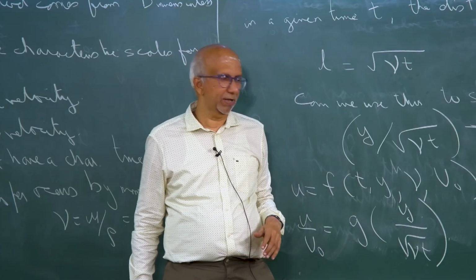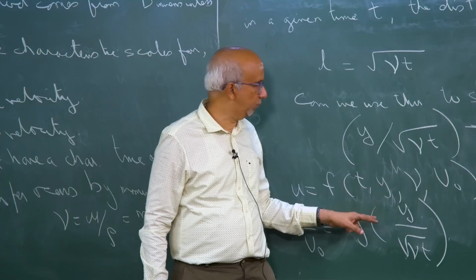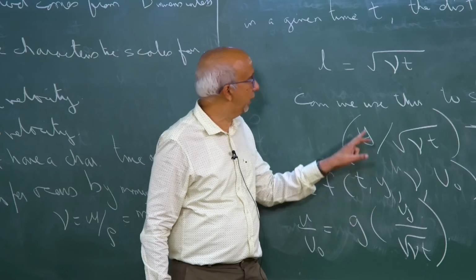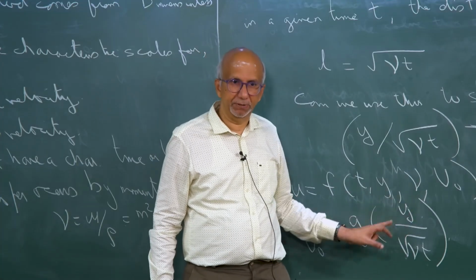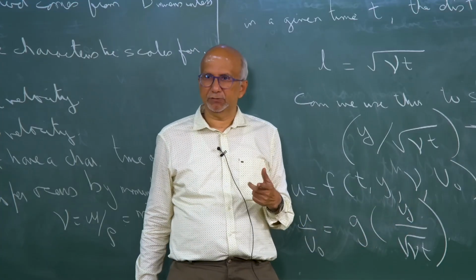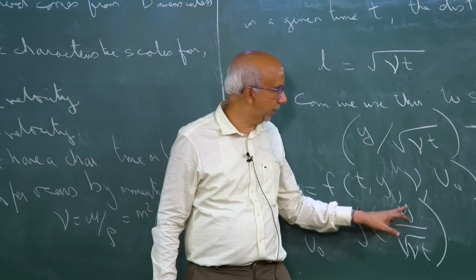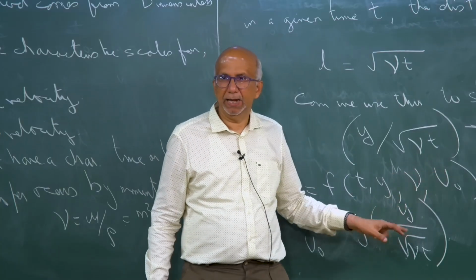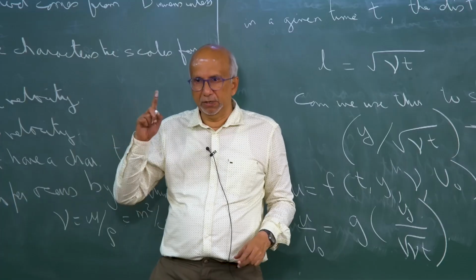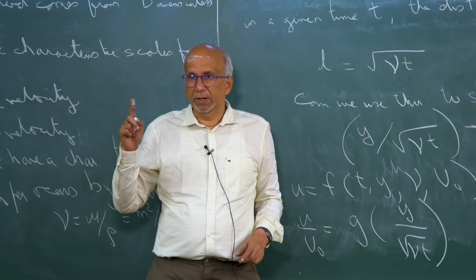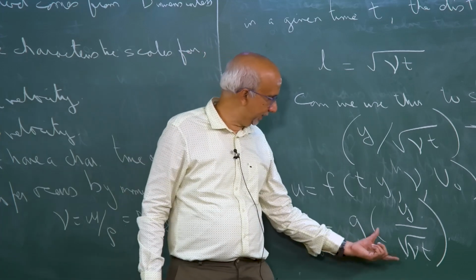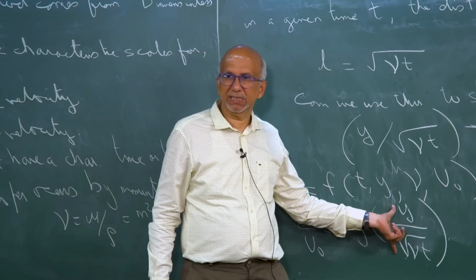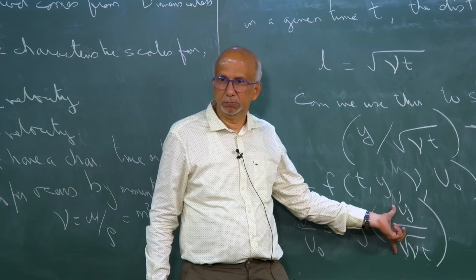Okay. So, if that is possible, then what I want to do is I would like to go back and make a transformation, relate t and y, and in my differential equation convert everything to my eta. Okay. So, what I am saying is I want to treat this as a group, as a dimensionless independent variable now.